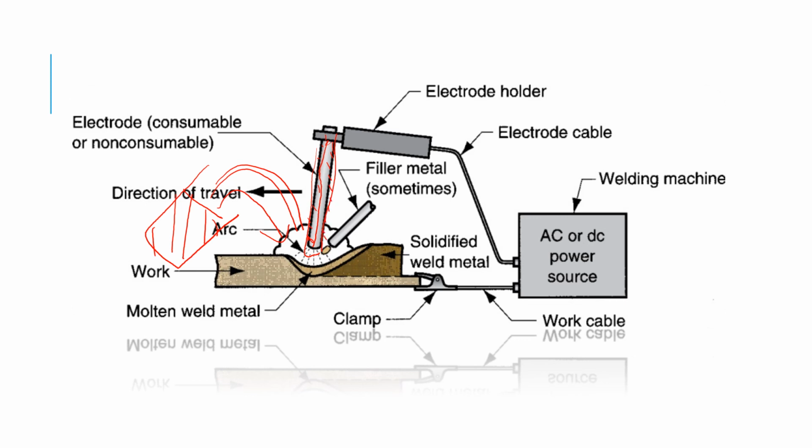flux. Okay, and the last one, you can also supply this one through, let's say, this area going inside here. So as for this electrode, if this kind of flux is to be supplied to the area, the electrode will have a hole in the middle here. So meaning that during the process, flux will be supplied in the center here, so that it can come out in this area, okay, during the process of welding.